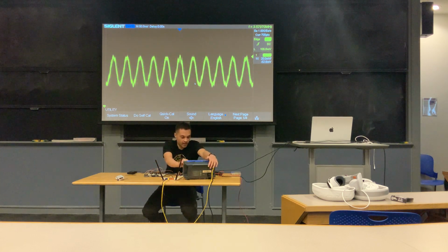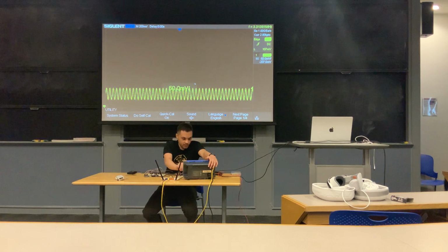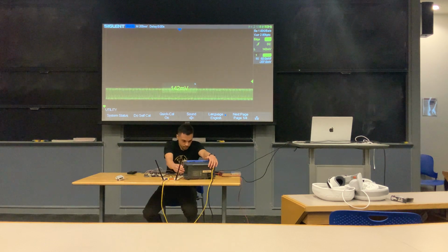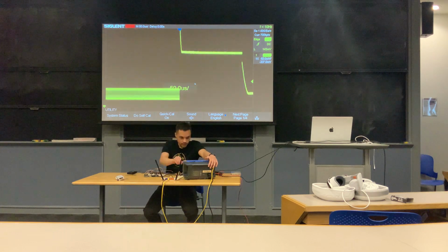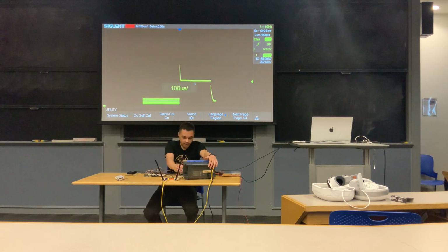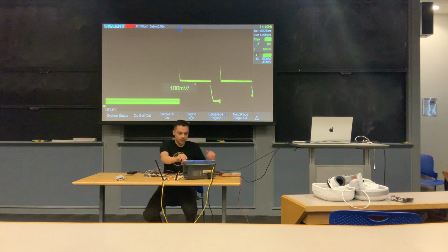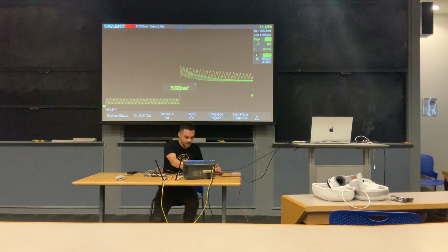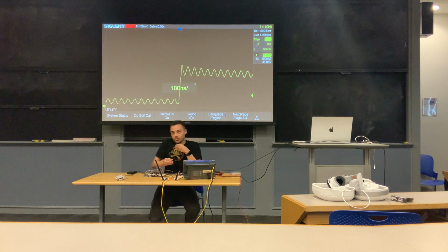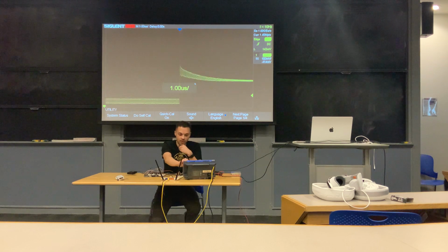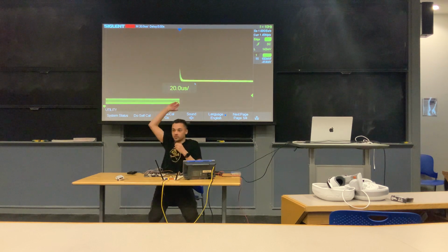So let's get a better view of that. We'll zoom out a bit, and we'll set a trigger up here. And so you can see this is what a fault looks like. I didn't actually capture enough. Do it again. And so we go from this very nice, normal clock in some normal voltage range to just shooting up to a massive voltage. Because we bring it up to VCC.